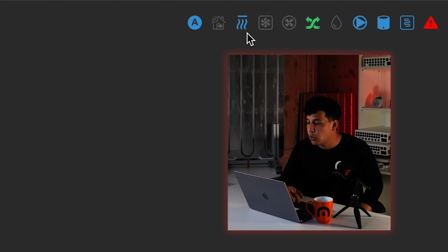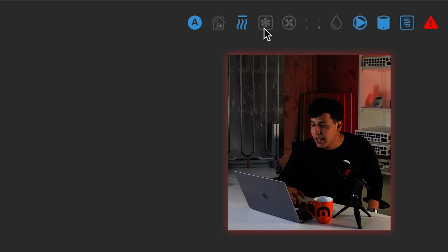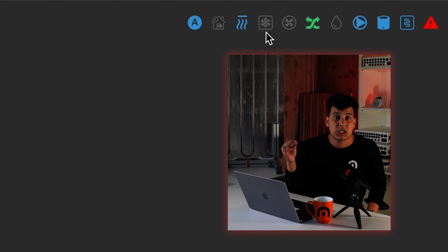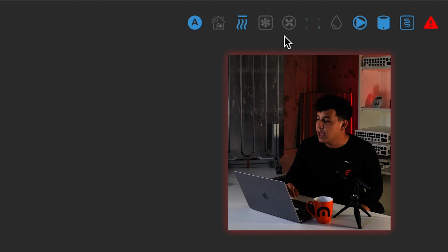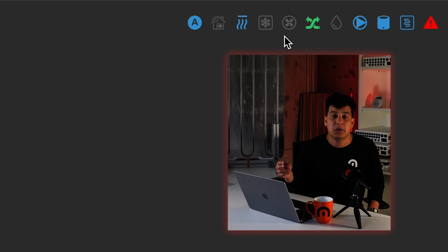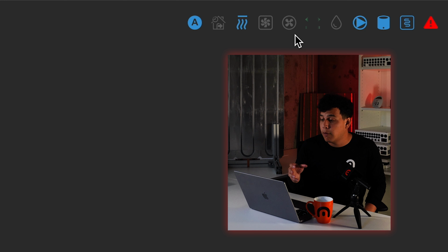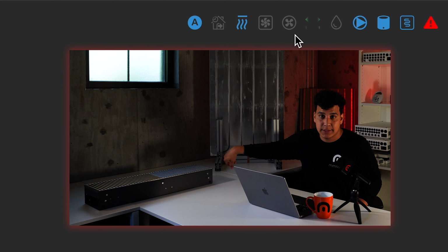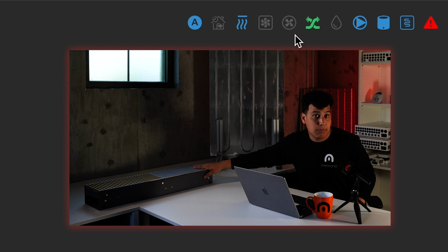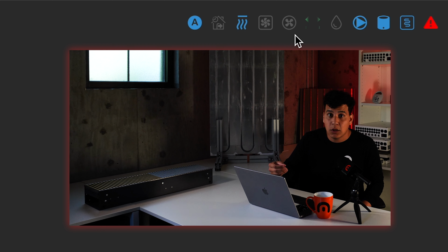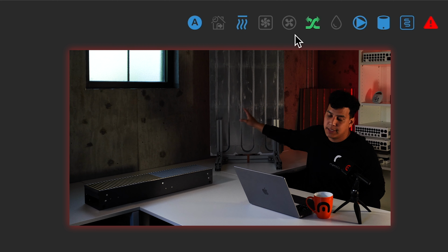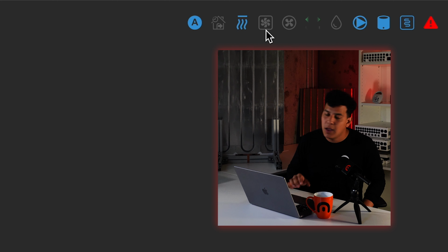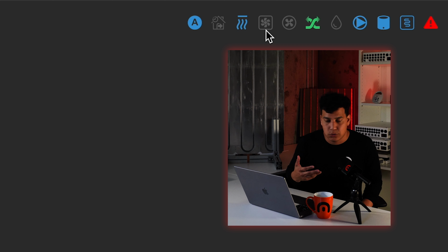And then you also have fan coils. When you have a square around a fan coil, that means it's a first stage fan coil. It is responsible for a zone's heating or cooling. Whereas when it's a circle, it is second stage, meaning it is the backup system for a zone. These are hydronic fan coils. They use the same hydronic lines as our panels, but they can be used for a zone to completely meet loads or just to supplement a radiant system. And so that's the difference you'll see here. Once again, they can be orange or blue for heating or cooling.